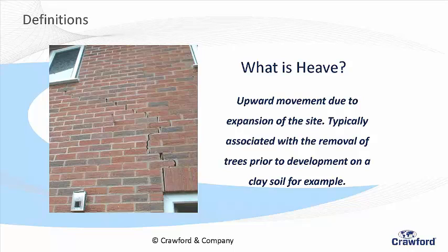And heave damage looks remarkably like subsidence, you might say. People say sometimes it's wide at the bottom, narrow at the top, not all the way. And my guys, when they look at this, they'll say, oh, not sure, could be, could not be. They won't put the flag on it and say it's heave. They'll come back to the office, make some inquiries, probably look at some aerial photos, some historical photos, do some research and development, and then they'll say, I think it's heave. Much harder to call, by the way, okay?